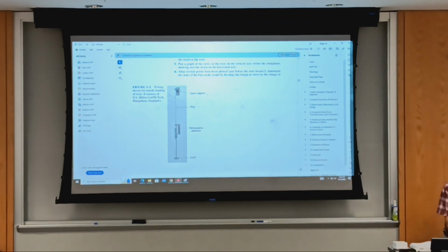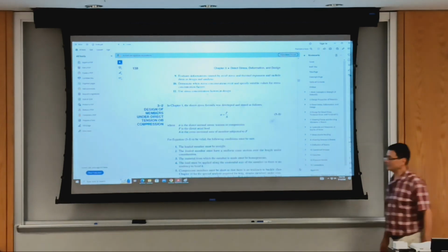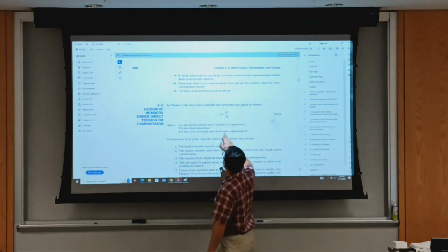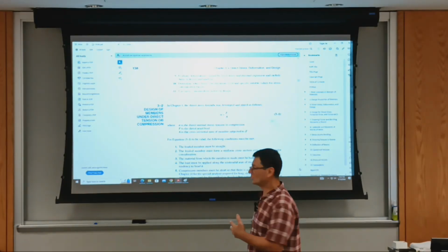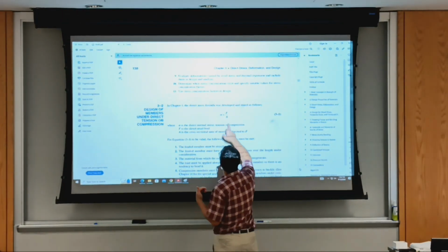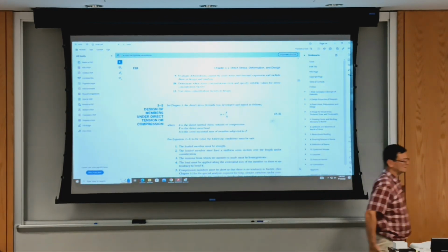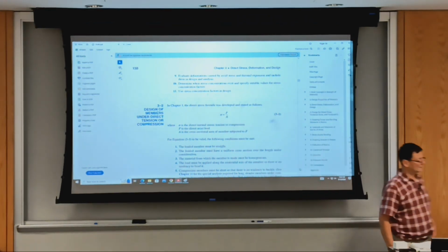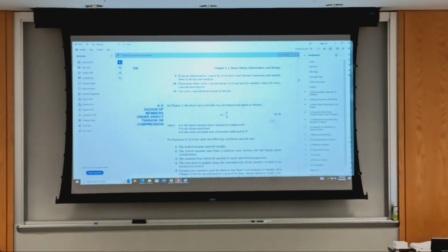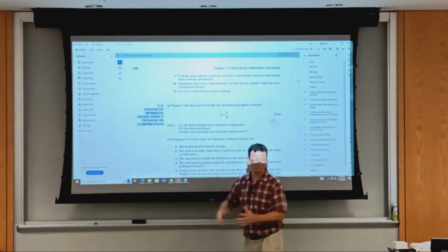Okay, so we've seen this before. To calculate direct stress, it could be tensile or compressive. You divide the axial load by the cross-sectional area. You saw that in the tensile testing, the stress is calculated with the area as is, no correction for its change, although it can happen for large deformations. But the assumption is that there's no additional effect. You don't induce bending, and it can happen rather easily.